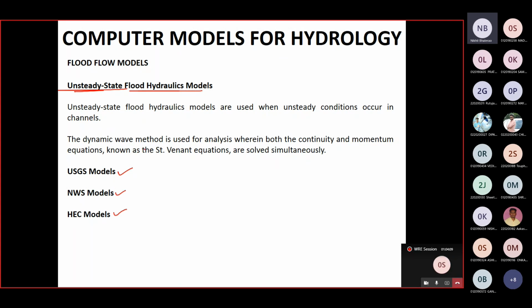In this case, the dynamic wave method is used for analysis, wherein there are both the continuity and the momentum equations, which are known as the Saint-Venant equations. These are used for carrying out the simulation in this particular case.